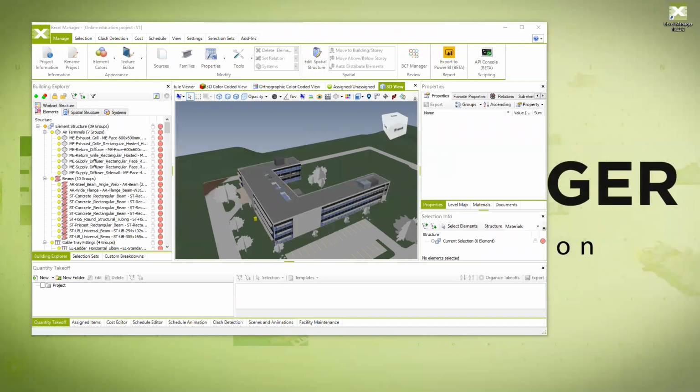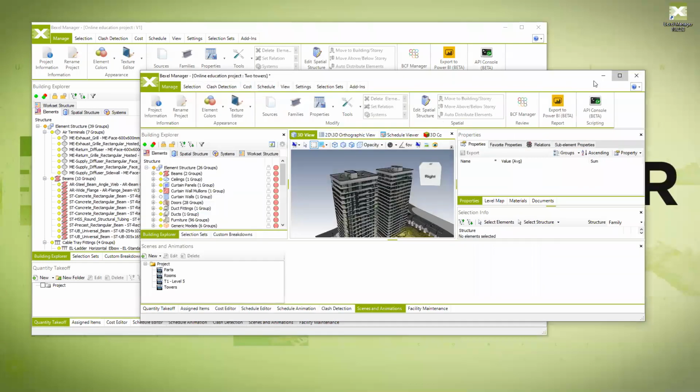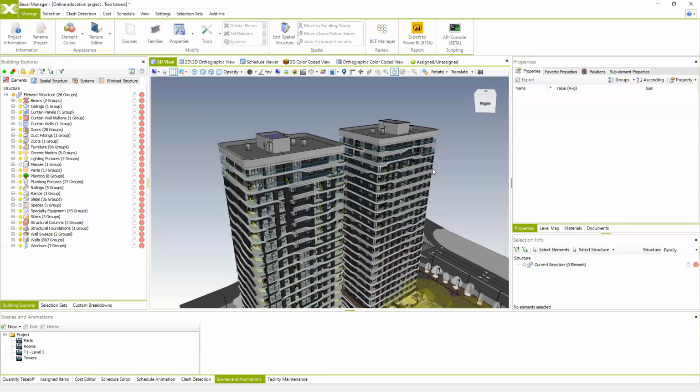And also, I'm going to answer the last question from the last session: how we can work with BIM model elements which are in the authoring tool, let's say some kind of compound elements such as compound walls, floors, ceilings. And as BEXEL Manager recognizes these layers from these compound elements, well, it depends how you export BIM model elements into IFC or into BX3.